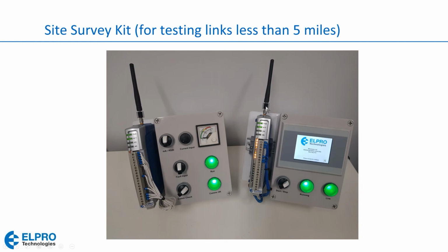Now, some of you might be wondering, what is this thing right here? That is a 20 decibel attenuator in series with the antenna. And the purpose of that is these radios are side by side. Normally they would saturate and the signal would become too strong and it may become intermittent. So by sticking our attenuators on, we're able to have these radios operating side by side and the received signal strength in our desired range.